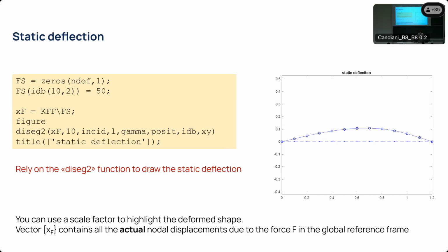Remember in this case that the results that you get will not be a mode shape, so it's not scaled by any quantity. The displacement values you get from that formulation are the actual displacements of the structure, because you're giving it a certain weight, so we shall expect a certain displacement. So it's not a non-dimensional transfer function, it is a displacement.